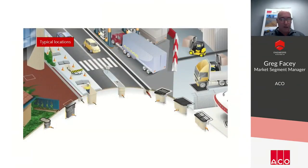So location determines choice. In a landscape application, with a light duty loading on a pit structure, a flexible pit can be used. When we talk about flexible pits, we're talking about plastic single wall pits. These materials range from fiberglass, so a resin and glass mat structure, or plastic, which is what we typically see in rotational or injection molding processes. But the advantages are they're light, robust, and easy to use.